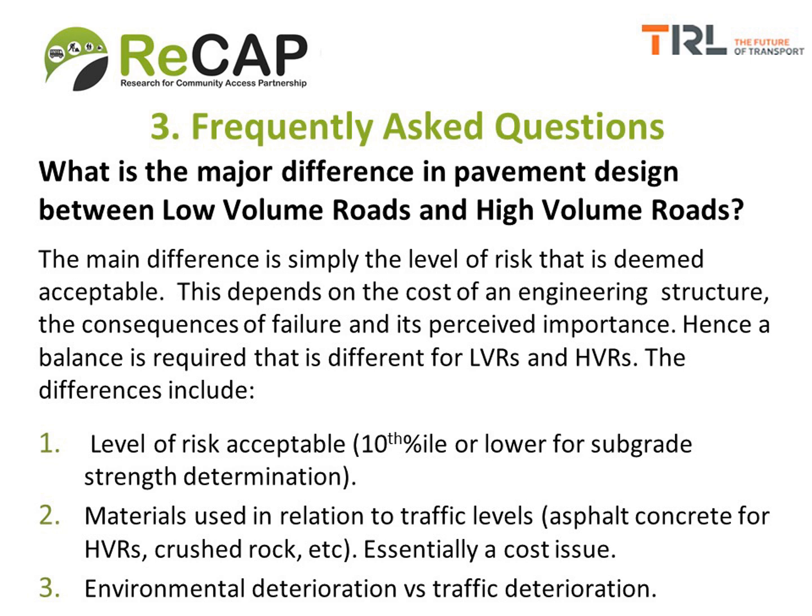And the other difference between high volume and low volume, we've said before, is that low volume roads are not carrying the very heavy traffic, so environmental deterioration is probably more important than deterioration caused by traffic. So we emphasize the environmental conditions and the designs that minimize environmental deterioration, because that's more important than the traffic deterioration, provided you're not getting all the overloading, which is always a proviso.